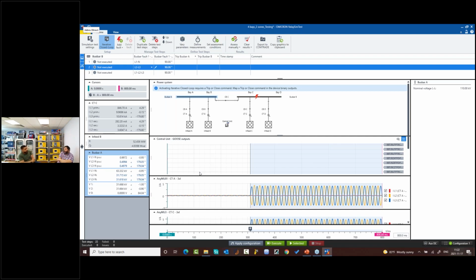This is a good question, really, but this requires a license. If I have a license, like what I have now, I can export the ComTrade, as you can see. This ComTrade data will be in a ComTrade file, which you can use in Advanced Transient as a playback later on. Exactly. And we already had a webinar before regarding playback.